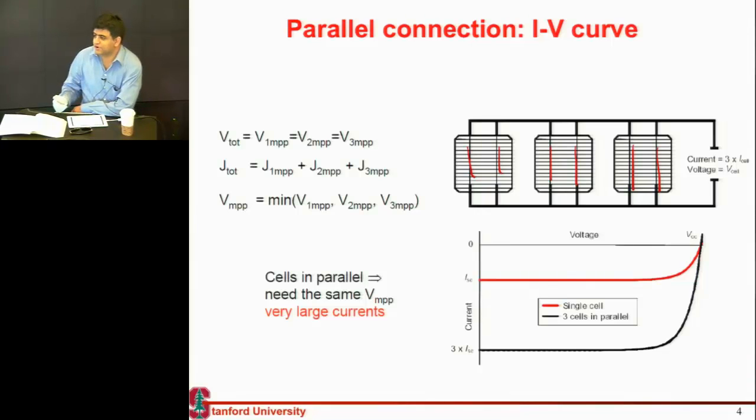So it's more of a practical reason, and that's something you'll realize when you do your project where you solder these individual cells. It's designed from a point of redundancy: what if one of these connections gets open, or while assembling them, what if you don't connect one properly. To build some redundancy into the system, that's another reason why you typically have 2 of these bus bars per cell.